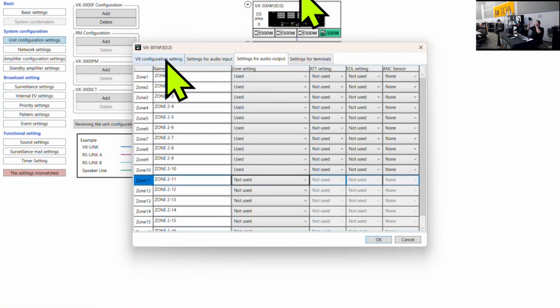You have one amplifier output and the speaker selector selects which zone it will go to, or all of them. So why is the VX2004 more powerful? Because each individual zone can be powered by an individual amplifier. But the 2008 and 2016 are powered by one amplifier at a time, for all zones. So again, it depends on the requirements of the size.